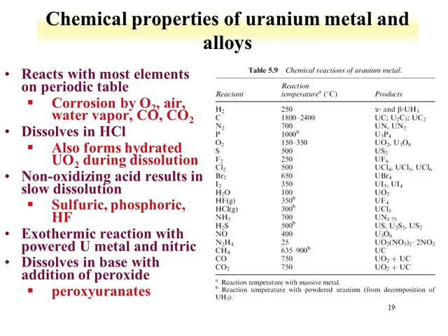The chemical properties of uranium metal and its alloys are listed here. Uranium metal reacts, and you can form alloys or intermetallics with a lot of the elements on the periodic table. The metal itself can be corroded by air, water, even under elevated temperature with carbon monoxide. This often means that if you store uranium metal, you store it under oil, so it prevents air interactions.